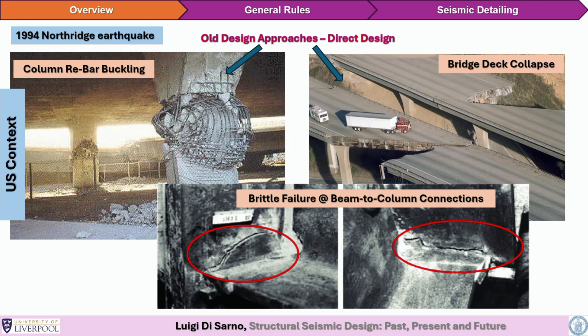Now, in terms of response of structures, moving from early applications: before 1994, there was the typical approach with no ductile basis, so there was no capacity design enforced in seismic design. In fact, in 1994, again the Northridge earthquake, which also had a very severe vertical component, showed that details on bridge piers, as shown here, were not effective. All the bars buckled. More importantly, looking at infrastructure, we are discussing these days resilient infrastructure, and they were not resilient at all.